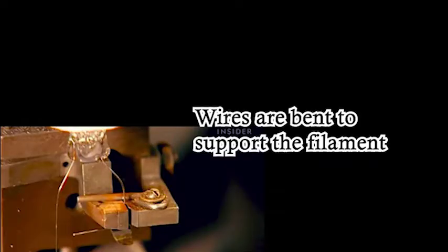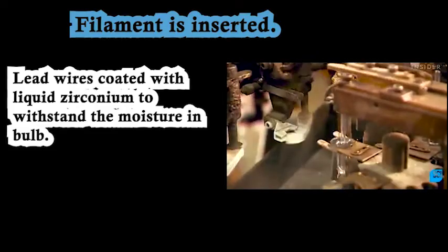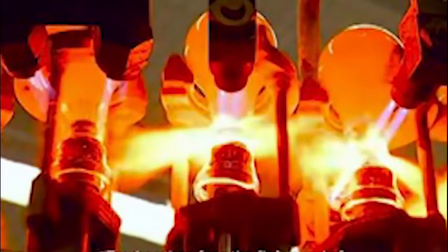After that, separate the lead wire and form the end into hooks. After that, we insert the coating of synthetic silicone, white powder, and spread it into a thin layer inside the bulb using the right amount of heat. Next, torch, then fuse the flat end of the mount to the neck of the bulb. Then vacuum out all the air and replace it with pressured argon gas. We must bend the lead wire and torch them to seal the exhaust glass, locking in the argon gas. Last but not least, insert one of the lead wires into the aluminium base in the middle and solder it in place. Finally, we test the light bulb and it is ready to package for the consumer.